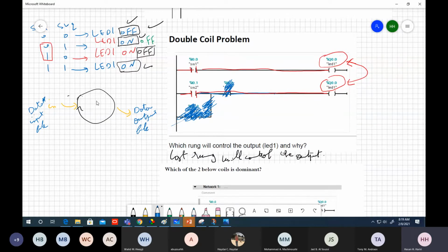And during the execution of the program, it's executed from up to down, from left to right. First, they collect all the input situations, so they know what they are. Then they start to execute. They find LED1 is Q00. In this case, the address is Q00. They put it 0, assuming we are in case 0.